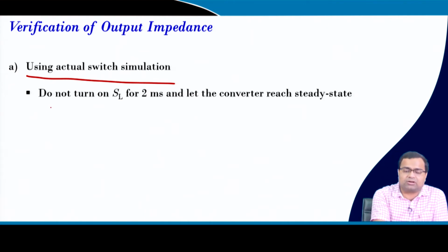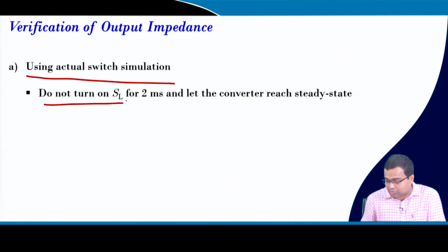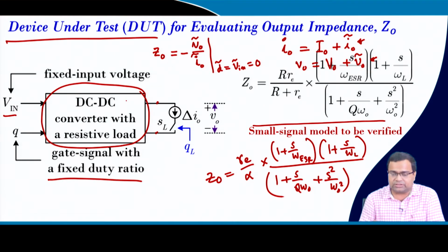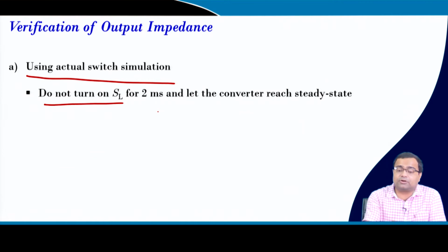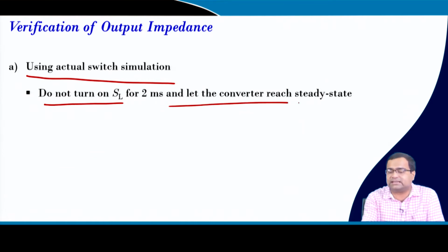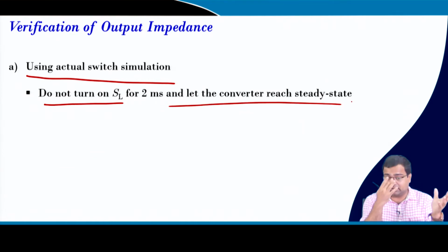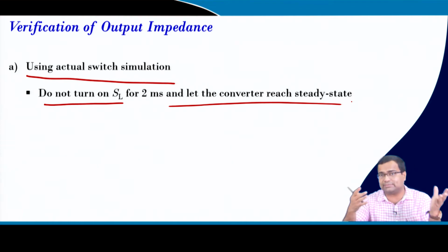So, we should not turn on the load, that means there is a load switch. Okay, this is a load switch, right. We should not turn it on for 2 milliseconds, and let the converter reach steady state, because if you turn on the converter, even a practical converter or a simulated one.